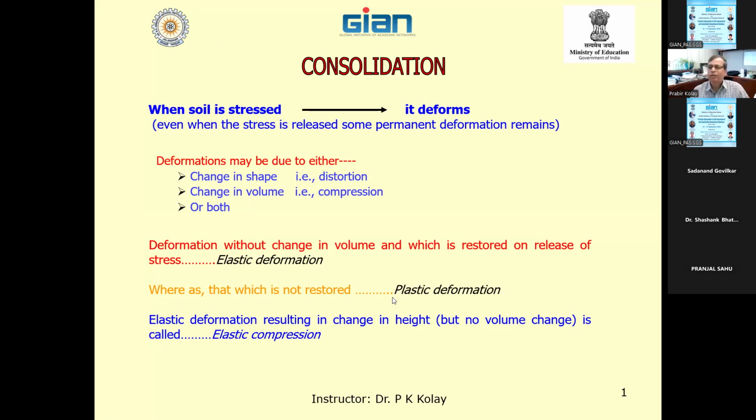Okay. So consolidation, again, I'm not going to go into detail, because this topic is mentioned as consolidation of soft soil. Consolidation of clay is basically the expulsion of water from the soil sample. When you apply load to saturated soil, all the load is first taken by the water, and then it is transferred to the soil. It is a time-dependent phenomenon and it is not quick, because the permeability is low.